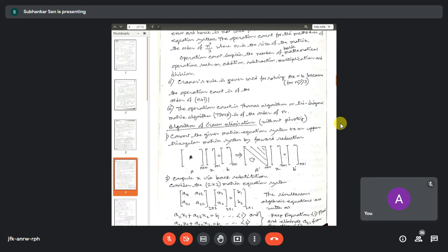I have told you in Navier-Stokes equations or in any full governing differential equation, we can have maximum 4 types of terms: unsteady term, convection term, diffusion term, and the source term. For example, if you consider the Navier-Stokes equations, for the unsteady term you can use backward difference or forward difference. We have already discussed FTCS, BTCS. For the diffusion term, the term with viscosity or the Laplacian, by default you have to go for the central difference. For the pressure gradient, we also have to go for central differencing.